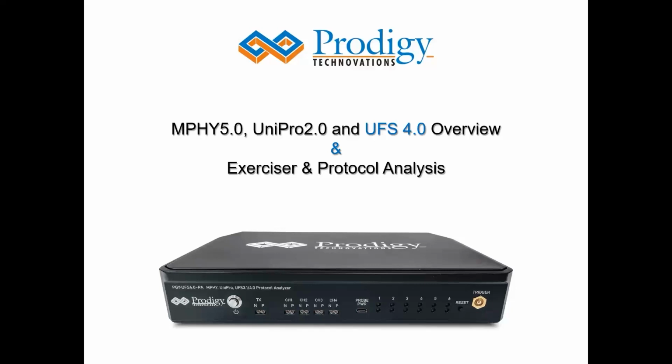M-PHY 5.0 has a data rate of 23.32 gigabits per second. Some of the unique features of M-PHY 5.0 are not just the data rate. There are new features like a high-speed link startup. Previously, link startup used to happen only in PWM Gear 1. Now there is an option available for all the lanes of M-PHY 5.0 to do the link startup at high speed.